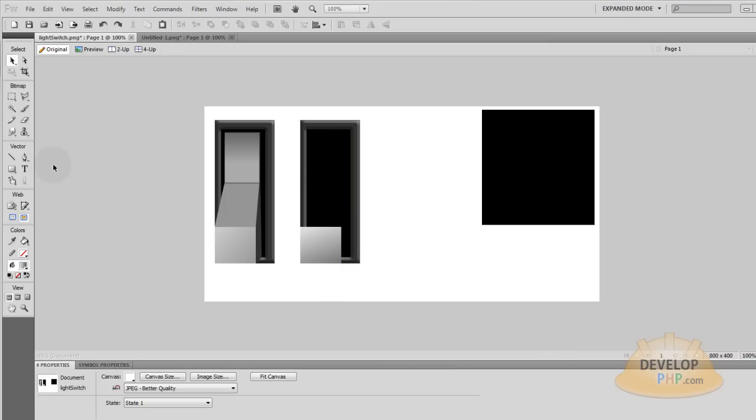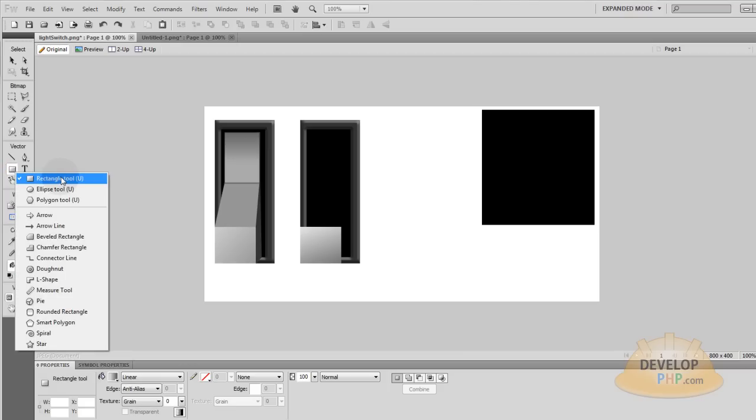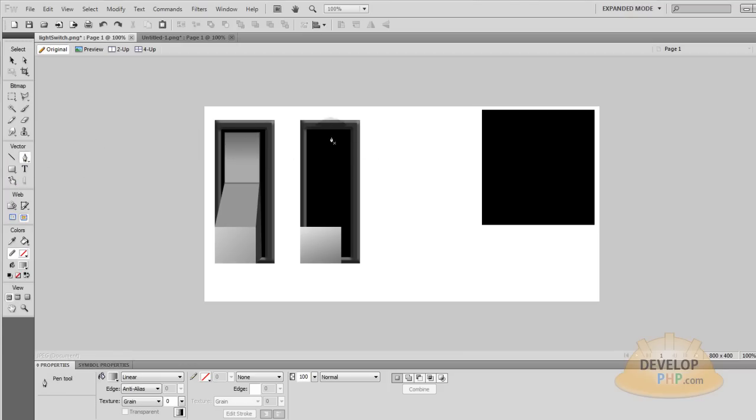Now I'm going to draw the top shape, which is a rectangle. Or you can use your pen tool as well. I'll show you. You can just grab the pen tool, and I'm going to start right about here to where it'll be about at this point on this one, but over here. Click down, let go, and you can hold your shift key if you want straight angled lines. If you let go of your shift key, it'll be a free floating line. But I'm just going to hold it down so it's nice and straight. I'll hold shift down, and I'll click down here, let go, keep holding shift. I'll go over to about maybe right there. It doesn't have to be exact. Remember, you can move your shape points around at any time.